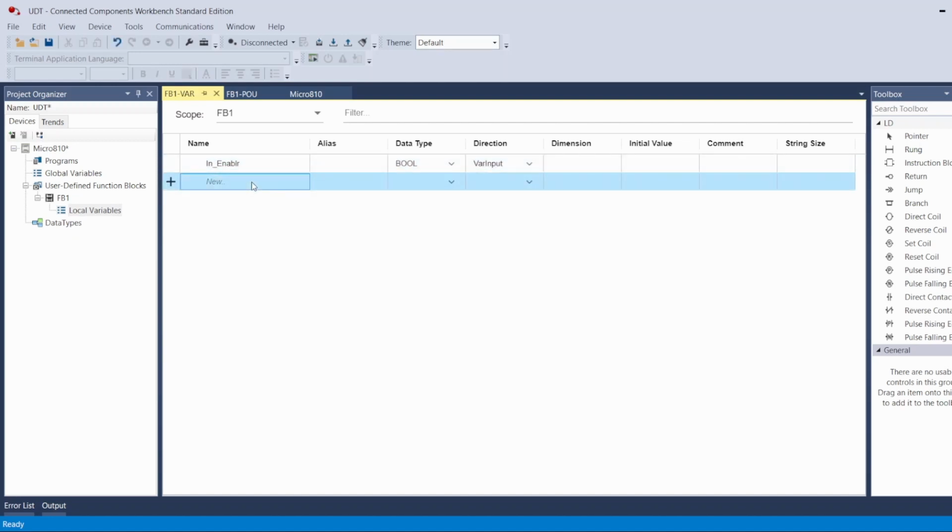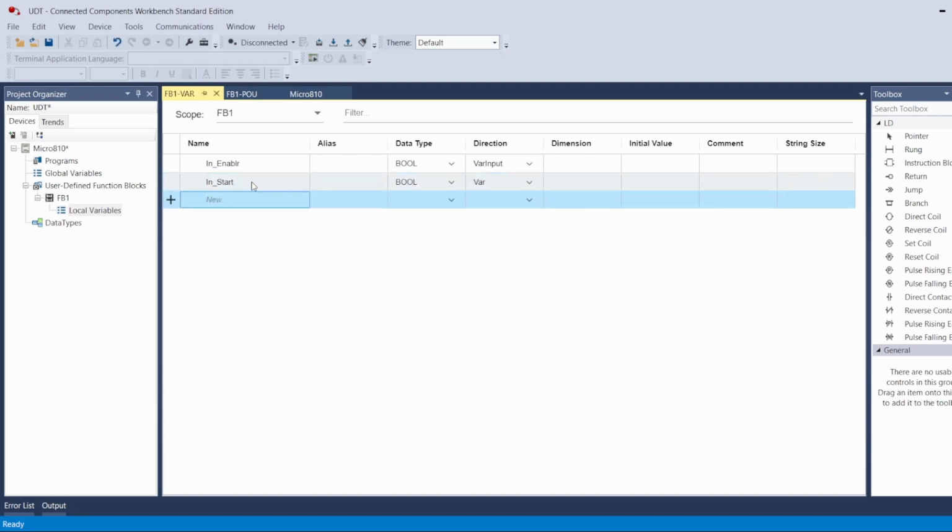And if you're still a little bit confused with what I'm doing, you will understand when I finish it. Second, I want an input that tells me to start the conveyor. Here I'm not saying conveyor 1 or conveyor 2, because this logic will be used for all the conveyors I'm using. It doesn't matter if it's 3, 4, 5, however many conveyors I'm using. So I'm not going to assign any conveyor number to this logic yet. You will see why.